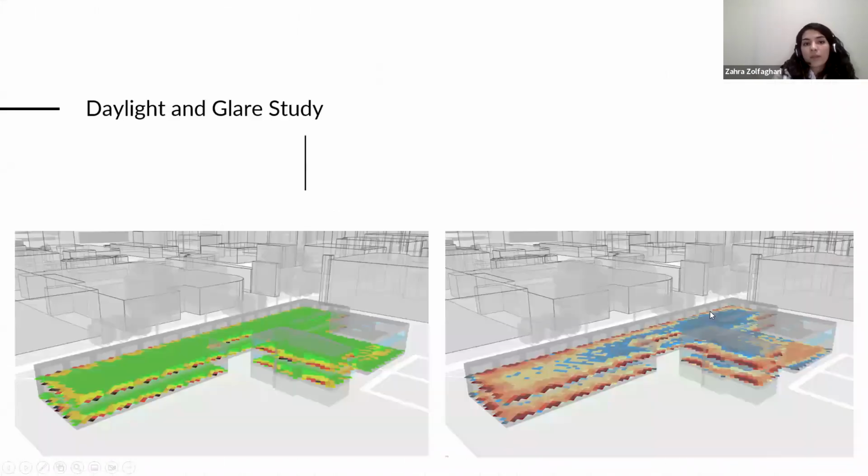Once you have your geometry in the tool, either by drawing it in the drawing tool or importing your geometry to cove.tool with plugins, you can run daylight and glare analysis to see how much daylight the indoor spaces receive, and also the glare risk. The carve-outs from the initial geometry in this project really help with improving the SDA and ASE points to increase daylight availability inside and reduce the glare condition.